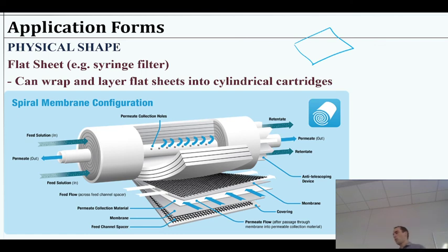But you could wrap it. In fact, you could wrap it with several membranes. If we take a look at what I'm doing here, we can take it and wrap it with multiple sheets. So long as we have the correct plumbing in between to make sure that once water passes through, it's guided along through a kind of freeway inside, and that's what you see in this picture up here. There are channels inside these layers, right? So once they pass through a membrane, then they'll be allowed to spiral their way into the middle to be collected. Otherwise, water is just going to carry on through.